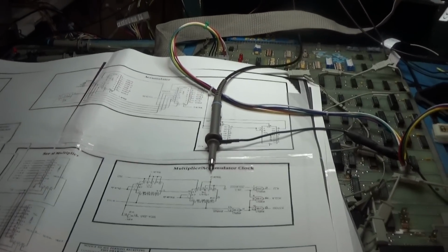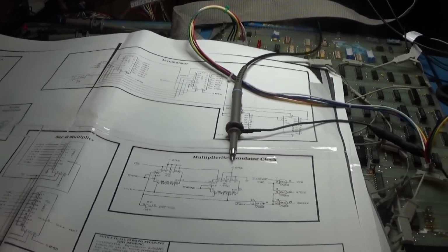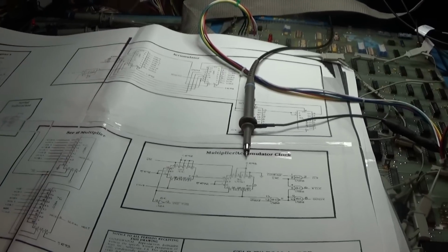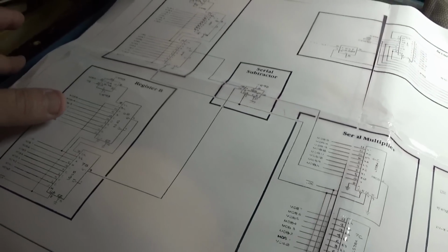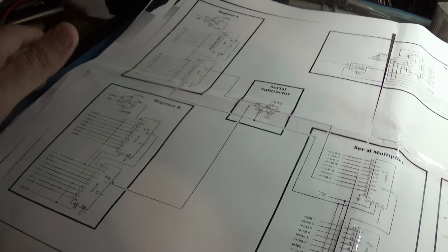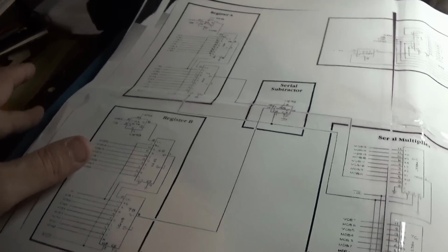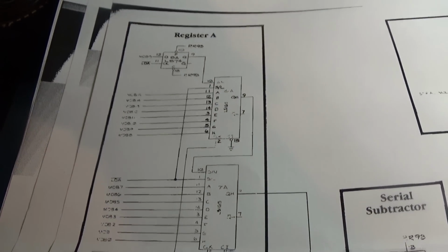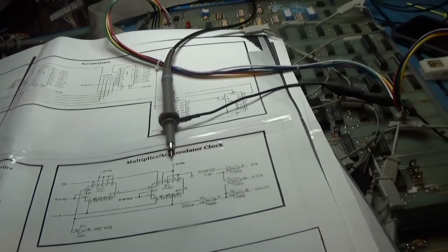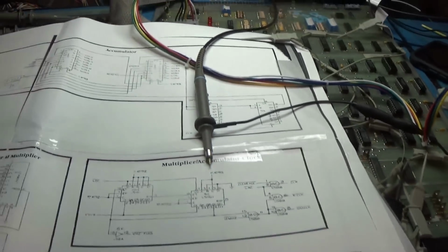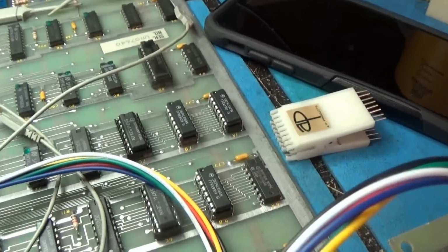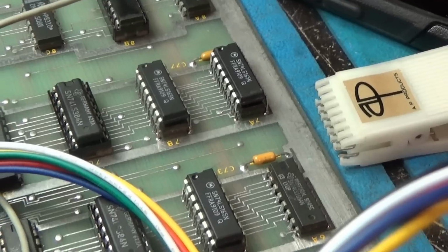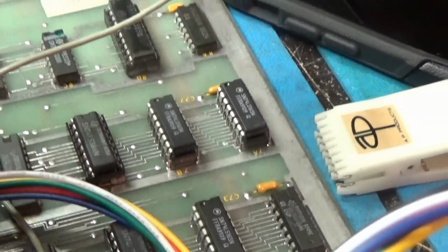So I went to the more complex type chips, if you will. These are registers. These are 165s, which a 165 is just a shift chip. So I started looking at these and I was like, you know what I'm going to do? I'm just going to jump these and see what happens instead of analyzing them. I'm going to see if I can get lucky. So I have one at a time jumped that one, and that one until all of the errors cleared up.